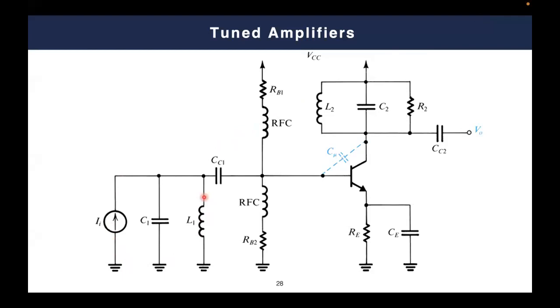So simply, we consider this what we can call a cleaning filter. The role of this filter is to clean your source from any noise before entering the amplification stage. Because as you can typically expect, whenever you have noise incident to an amplifier, this noise will be amplified as well.